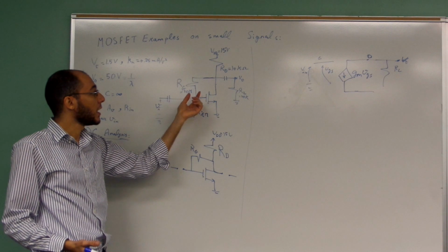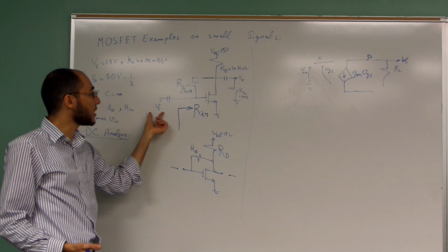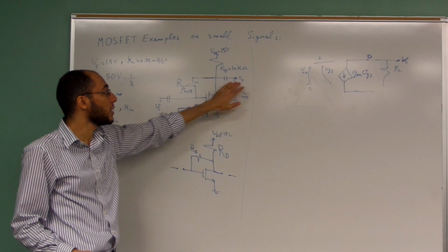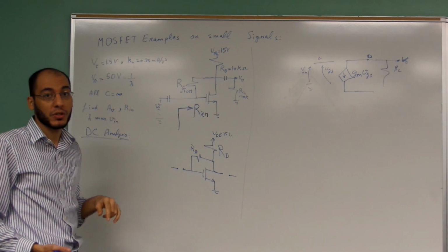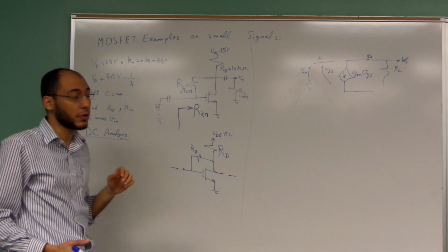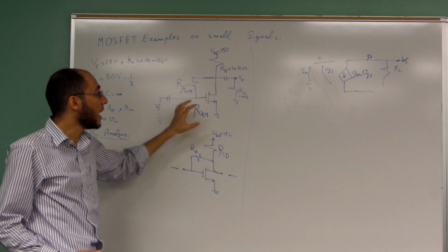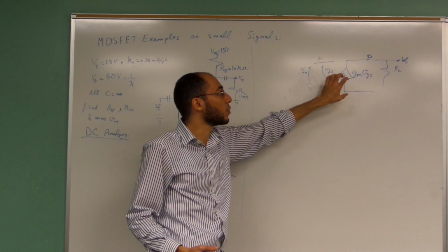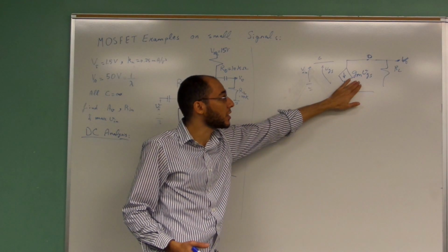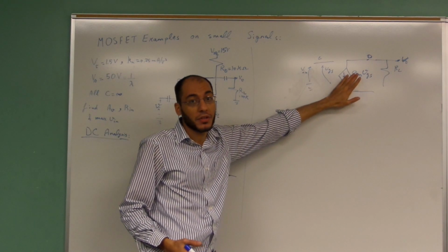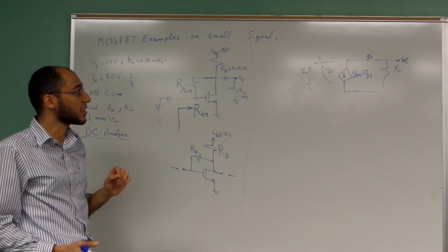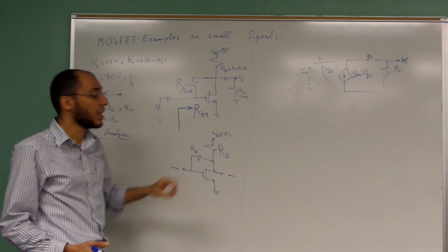The transistor is going to amplify the input signal to the output signal. So it's going to give me an output signal, which is an amplification of the input AC signal. The input AC signal is very small, and I want the output signal to be very large, and that's why I pass it to a transistor. And that's why I need to work on an AC equivalent circuit. And it turns out that the AC equivalent circuit is affected by something called GM, the transconductance of the transistor. Okay? And this transconductance is affected by the DC analysis.